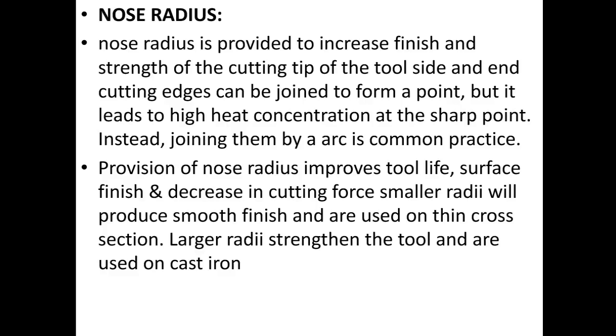Provision of nose radius improves tool life, surface finish, and decreases cutting force. Smaller radii will produce smooth finish and are used on thin cross sections. Large radii strengthen the tool and are used on cast iron.